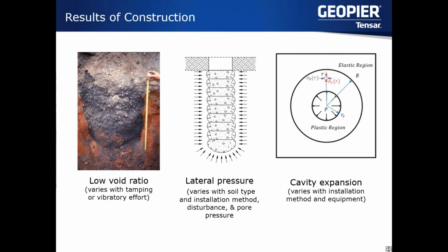So that's one way we might do it with drill and fill, is we might auger it out. But in the majority of cases, we're using a displacement system, and it'll either be entirely cementitious, or we might build what we call a grouted displacement pier. In that instance, we would flood the mandrel with grout and then introduce aggregate and build the aggregate pier as we normally would. So typically it's displacement.